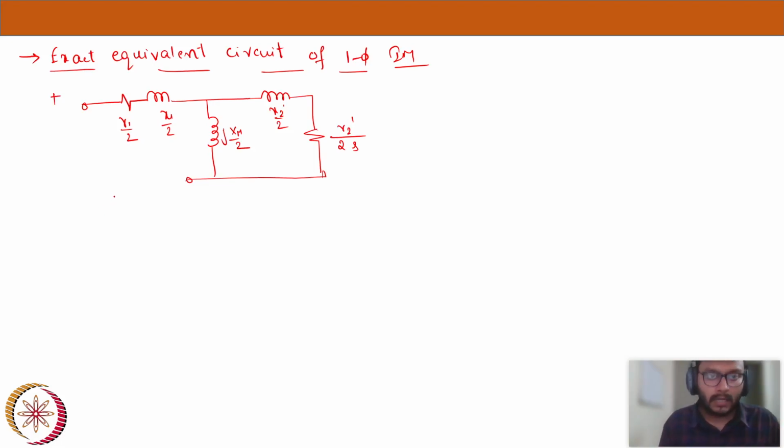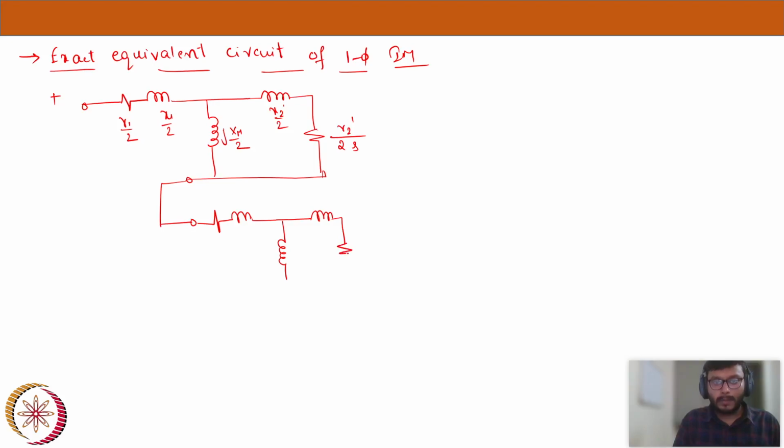I will write it at the end because we have another circuit in series with it. Now I am adding the other circuit in series. From here my negative sequence will start: R1, X1, and again the magnetizing reactance, and again the reactance, and this is the rotor part.